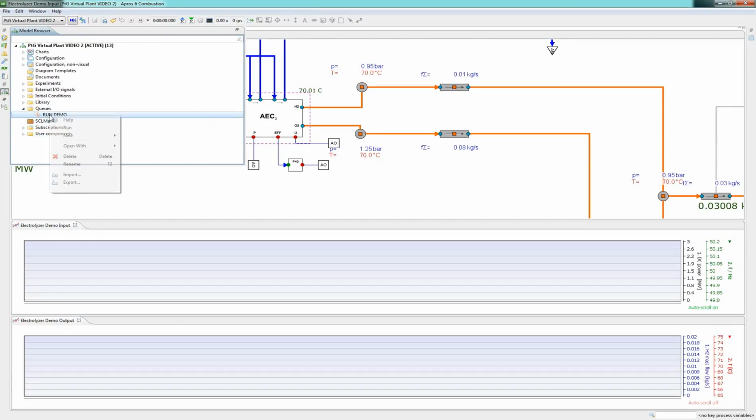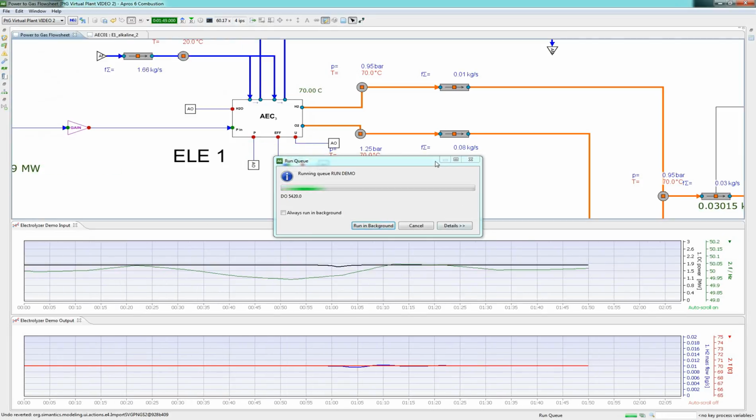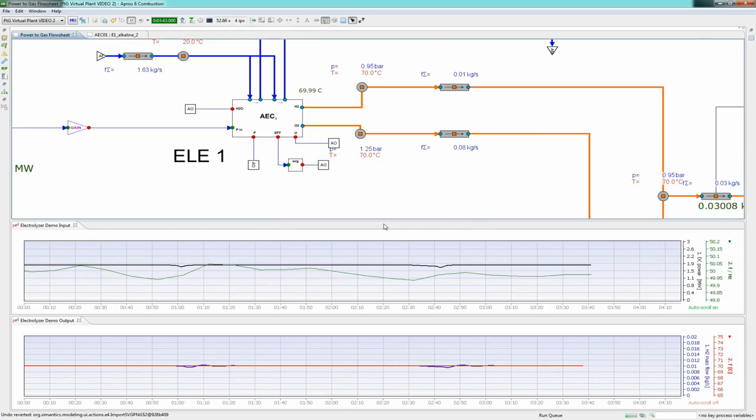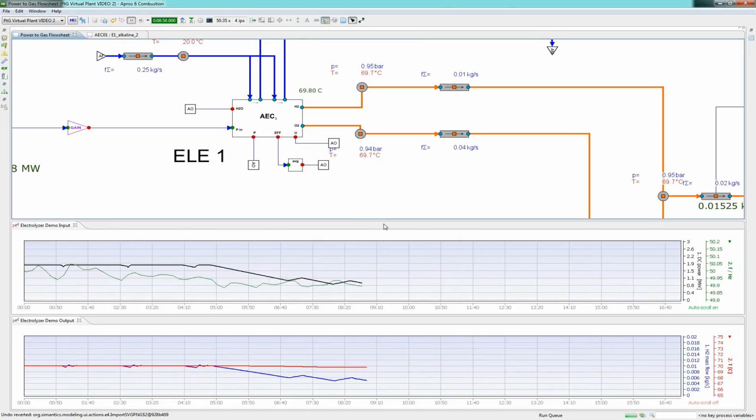In the simulation, the electrolyzer is used in electrical grid frequency support for the first 50 minutes. This means that the electrical power going into the device reacts to the grid frequency. Low frequency, low power, and high frequency, high power. There is a dead band around the nominal frequency of the grid, which is 50 Hz.